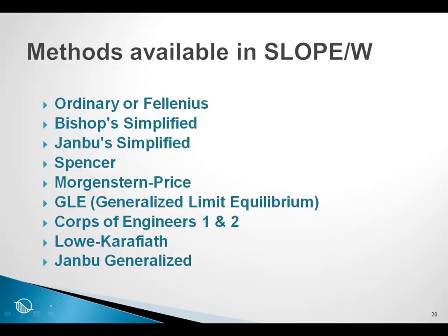In summary then, with these two factor of safety equations and the assumptions that are made about interslice shear, we can create the factor of safety for all of these commonly published methods: the ordinary or Fellenius, Bishop simplified, Janbu simplified, Spencer, Morgenstern-Price, and so forth.